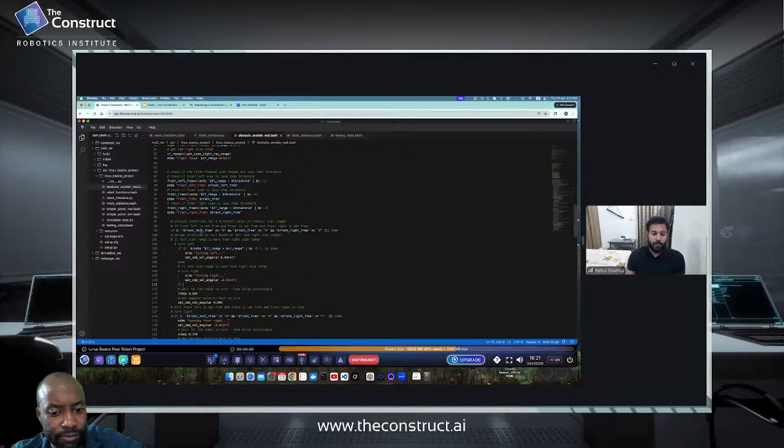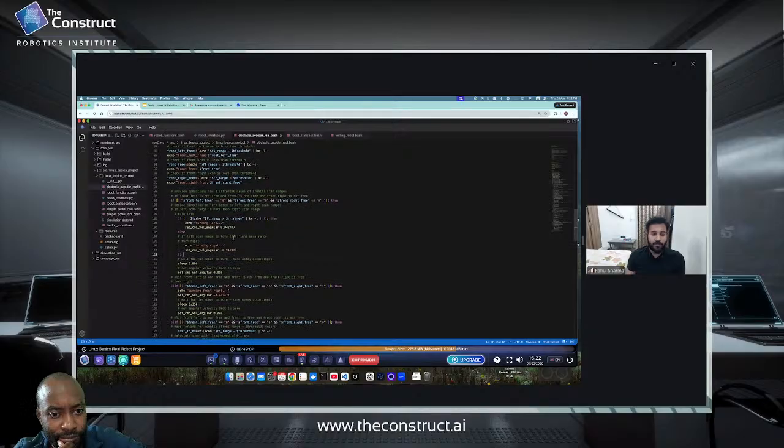First it will compare the front left. If it is 0, then here is also an obstacle. Then front, here is also an obstacle, and the front right, here is also an obstacle. So it will satisfy this condition. Since we have put the and, it will have to compulsorily satisfy each condition. Since all these sides are blocked, it will then enter into this code, which will basically compare the extreme left and extreme right range here through again this BC calculator.